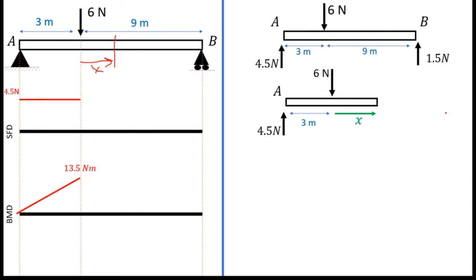And now I am going to mark the shear force, and I mark this point as Q. So this is the shear force I marked, V2. The moment due to V2 is in the clockwise direction, and M2 is a sagging moment for this AQ beam. So as I did before, here also I am going to find V2 and M2.